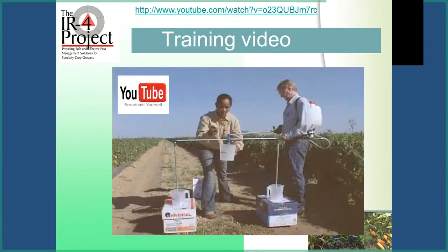So I hope you had a chance to look at some of the YouTube videos that we had posted. I provided links to some of these processes. So what you see here is a picture out of the video whereby they're calibrating a sprayer. When they calibrate, they're only calibrating with water, right? This particular sprayer has 3 nozzles. There's a nozzle here, a nozzle in here, and a nozzle in here. And so they're using these 3 containers to catch the output from those nozzles.